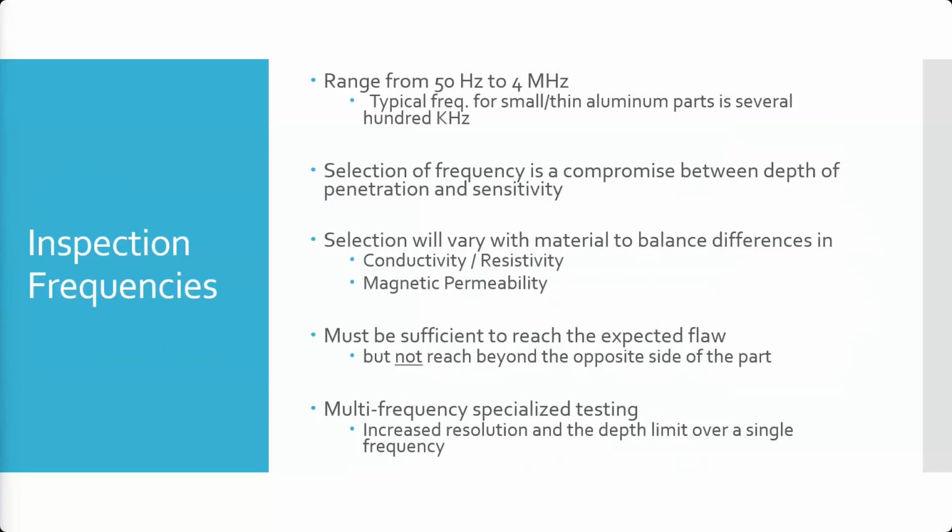So a very small crack beginning to form in it is a much bigger problem than a crack of the same size in aluminum, or even more so than a crack of the same size in steel. Right? The more brittle a component is, the more likely a small crack is to quickly form into a big crack.